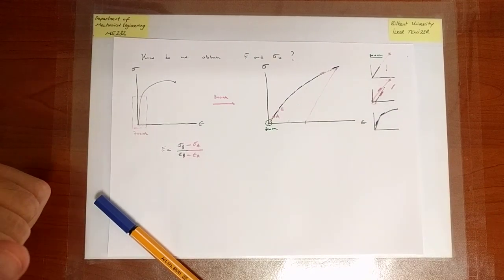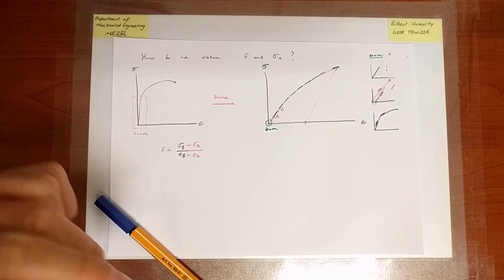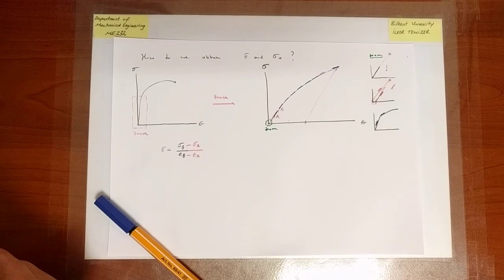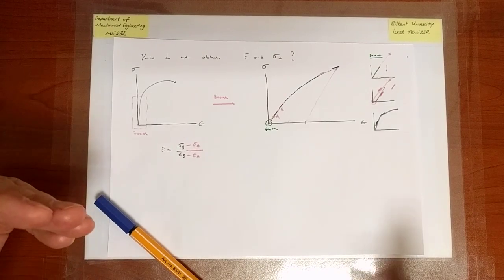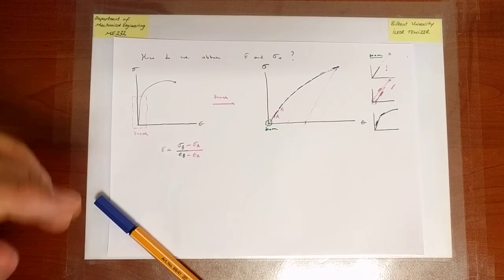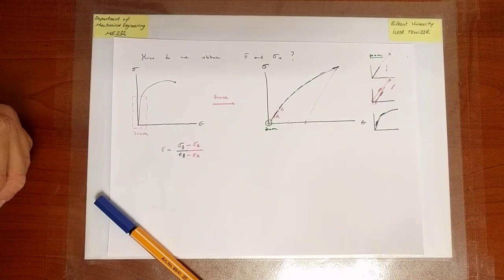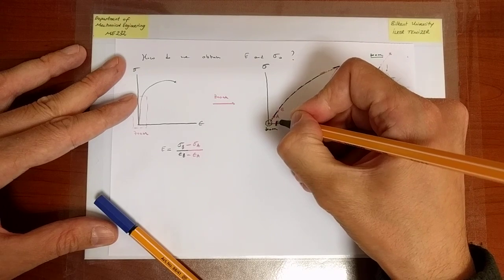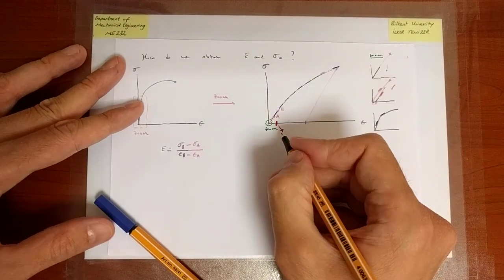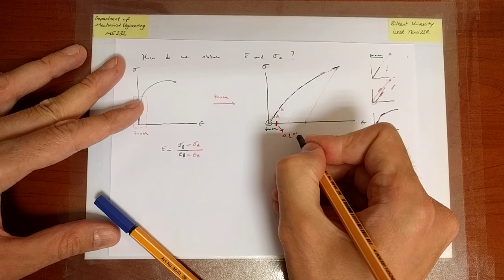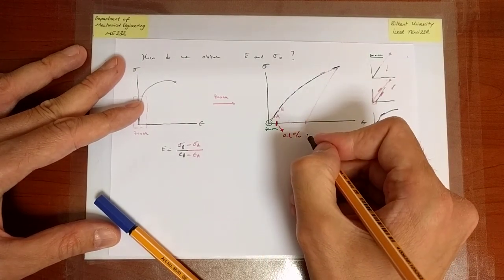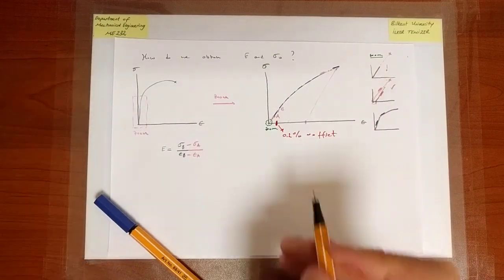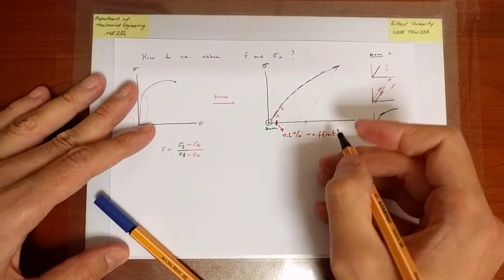So the amount of plastic deformation that we observe is an indication of the onset, or the extent, of plasticity. So people have said, well, let us agree on a very small amount of plasticity that will be indicated as being appreciable, so that we can be sure that plasticity has started. Okay? And that amount has been agreed to be, in most cases, 0.2% strain. Okay, this is called the 0.2% offset, right?